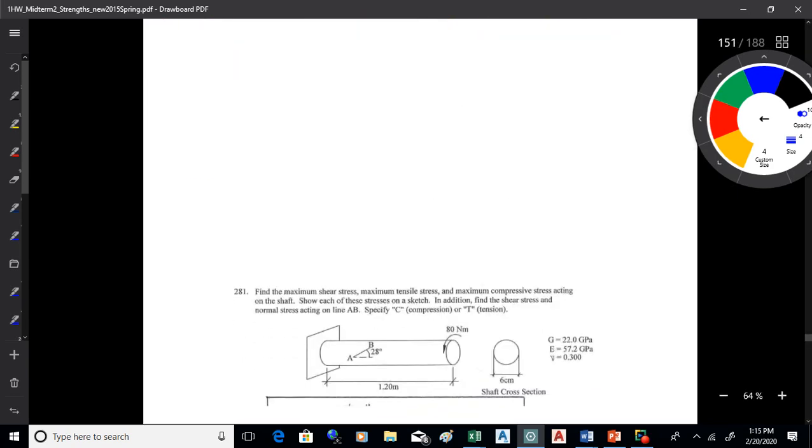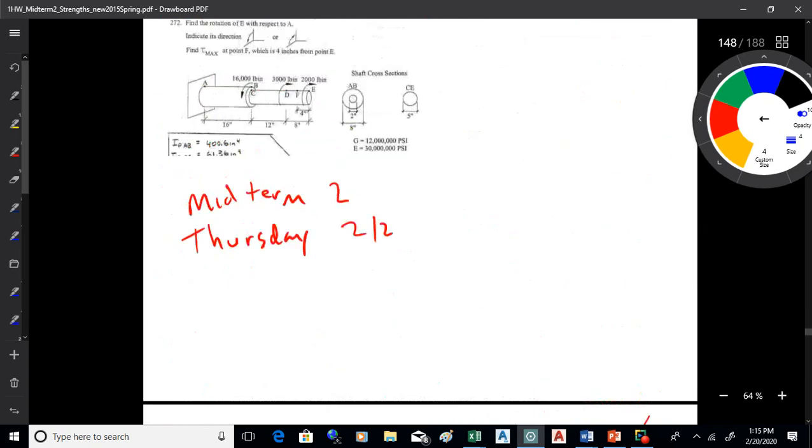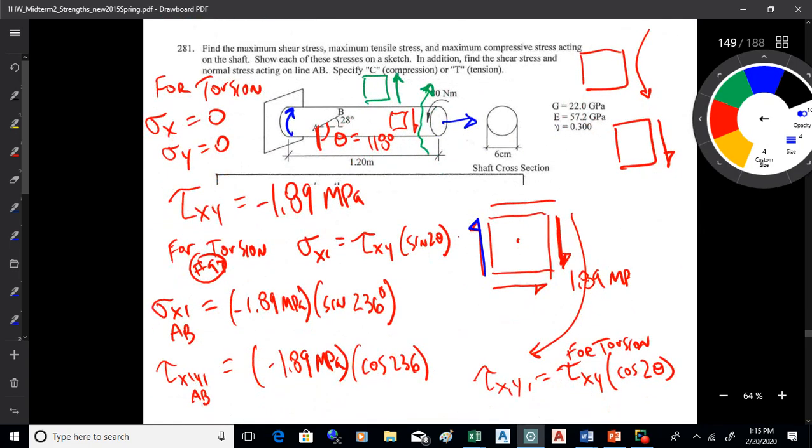We're good with that? I just want to point that out. And these kinds of details, just pay attention to them. They matter, okay? Keep in mind that when you're doing stress and biaxial, you always measure from the vertical plane. That's just the convention. It's not something that should make intuitive sense either. It's just how somebody set it up 150 years ago when they generated the equations. That's all it is, really. So, just remember it. Okay?